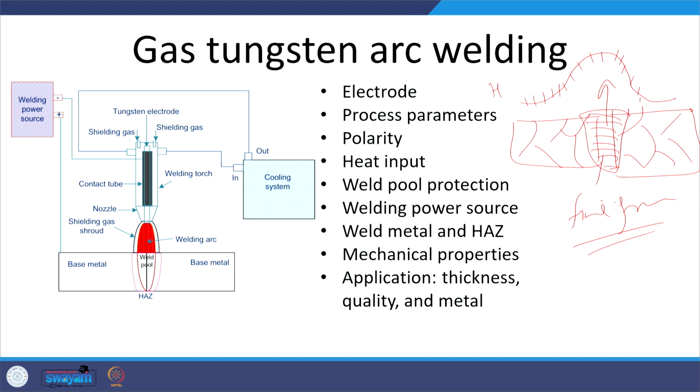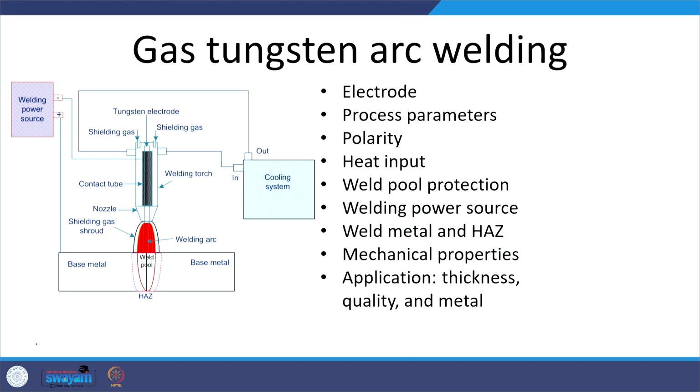But if it is steel, then certainly due to transformation hardening, the weld zone and heat affected zone will show a significant increase in hardness as compared to the base metal. This is attributed to the martensitic transformation in the weld and a little partial martensitic transformation in the heat affected zone. So, depending upon the kind of metal system, the mechanical properties of the weld joint will heavily depend upon the kind of metal system and its strengthening mechanism.